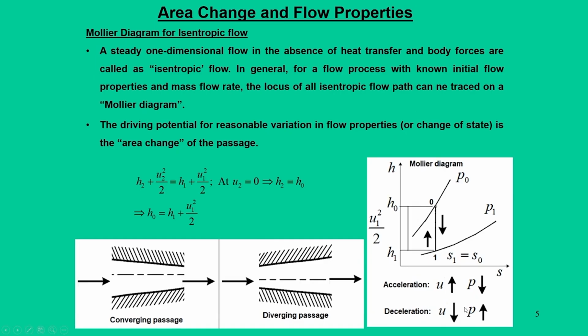So, this is the very basic theory for nozzle actions and diffuser actions, and this thermodynamic behavior can be replicated by designing the flow passage. Now, in either case the passage can be converging or diverging. Whether expansion or compression has to take place, in other words whether a diverging passage will behave as a nozzle, or a diverging passage can also behave as a diffuser, all this depends on the nature of the flow.